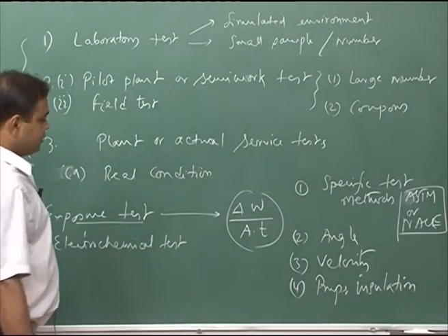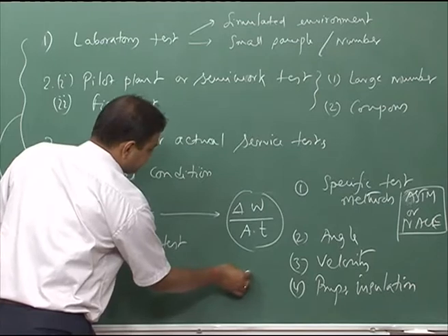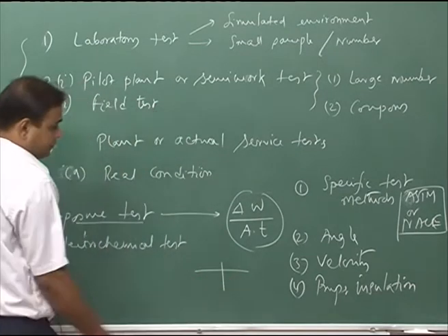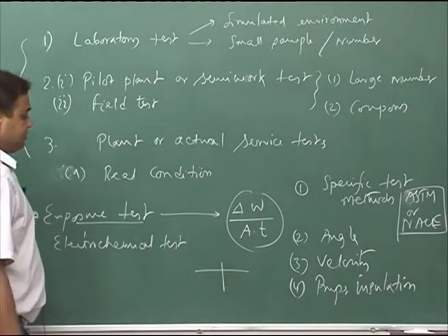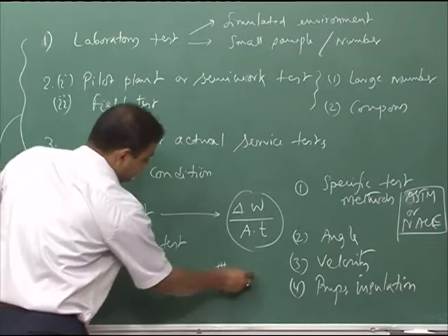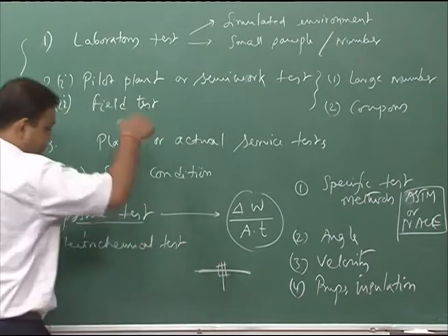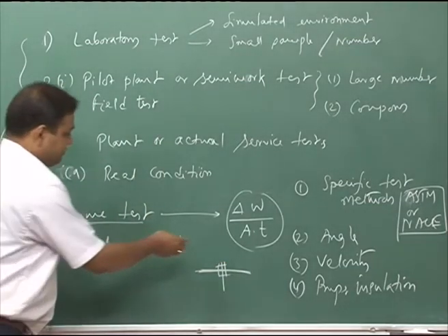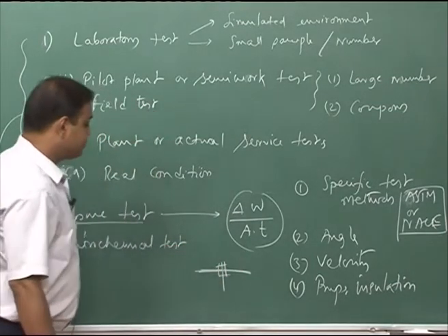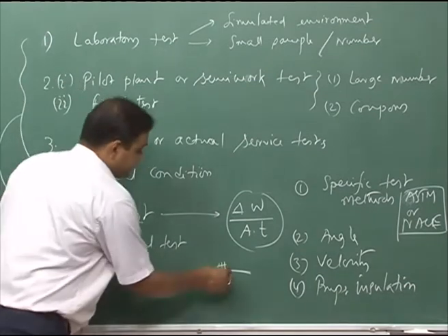Let us say the sample is exposed to the environment by hanging from a station. That part should be insulated, and if what it is hung from is a metallic object, then this connection should be properly insulated, otherwise there could be a galvanic effect.